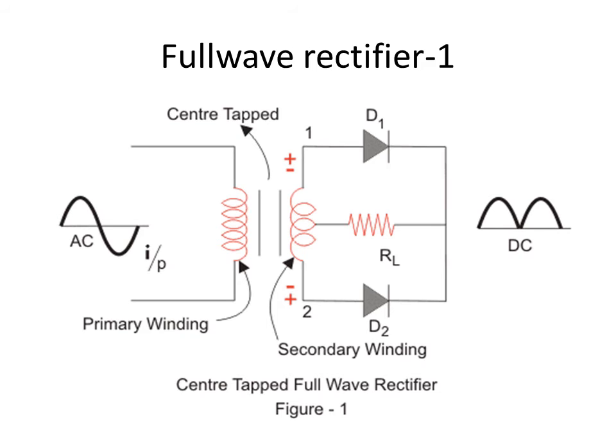So that means we haven't eliminated any half cycles when we are making a full wave rectifier. So that is the advantage of using a full wave rectifier over a half wave rectifier. And this type of circuit is only one option of making a full wave rectifier. We have got one more to learn, and that is the bridge rectifier.